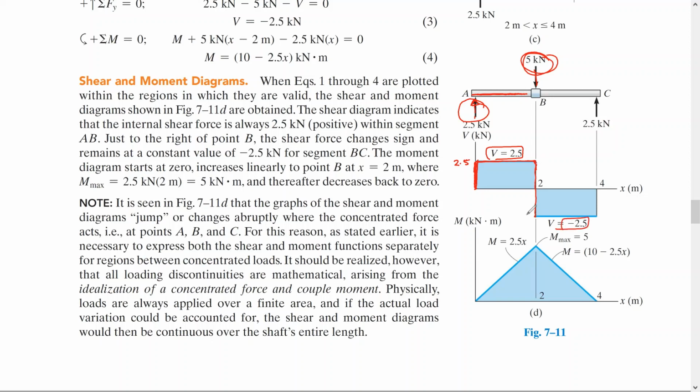هاي القيمة minus 2.5. اوكي، الآن كان نفس الشيء you're gonna keep straight لأنه أنت ما عندك أي load بالمنطقة هاي till this point. At this point you have a load upward 2.5. أنت هون minus 2.5 هون بتصير عندك إيش؟ minus 2.5 plus 2.5 بتصير عندك إيش؟ 0. So this is the shear. نفس اللي رسمناه هناك بالمعادلة.